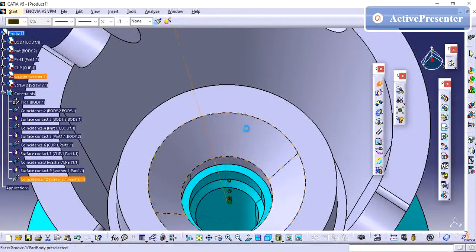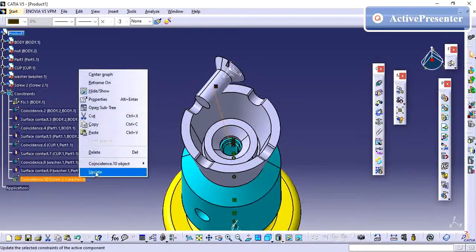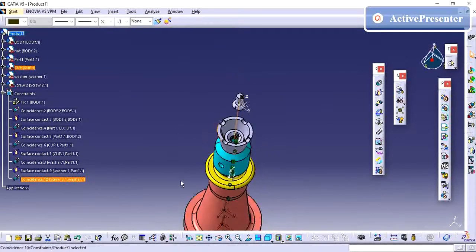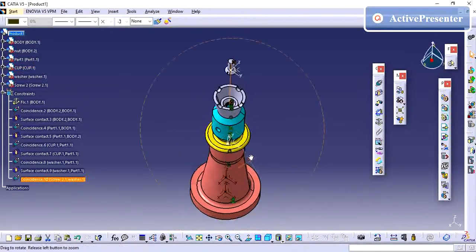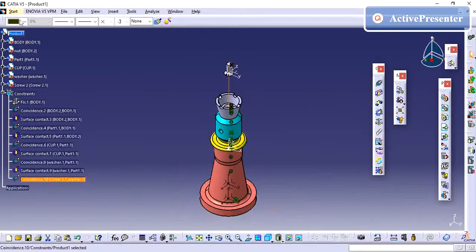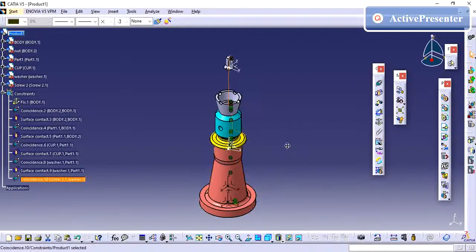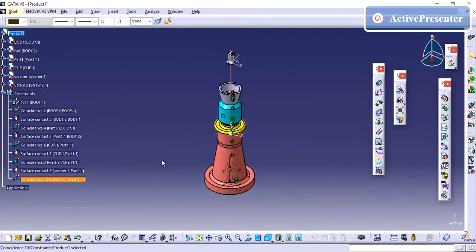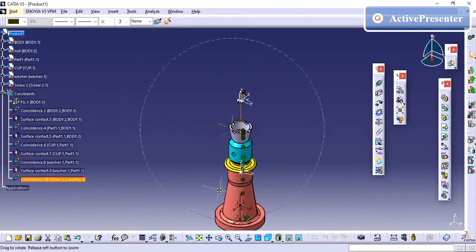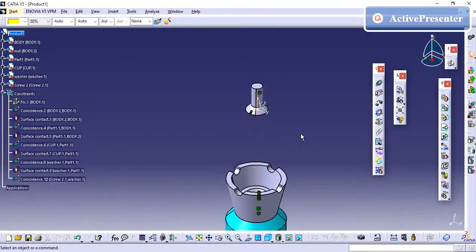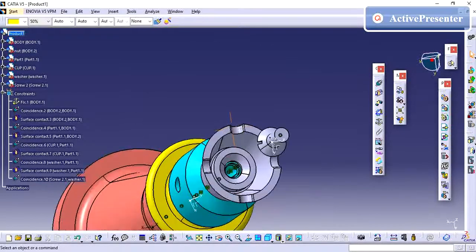If you are a beginner in this scenario, you will need to assemble the part with constraints. But in reality, if you work on automotive parts, the automotive tree structure, the assembly structure, won't have any constraints. It will have a working axis and a global axis. The global axis is default for all the parts and will be the same. The working axis will vary depending on the part position. In that scenario, we won't provide any constraint. By default, the part will come into position.